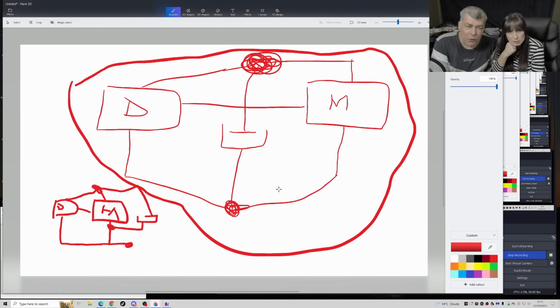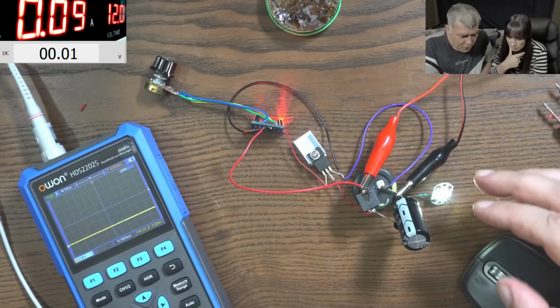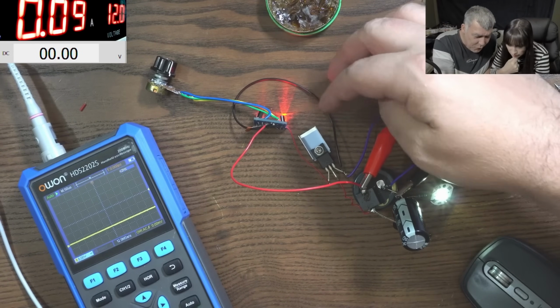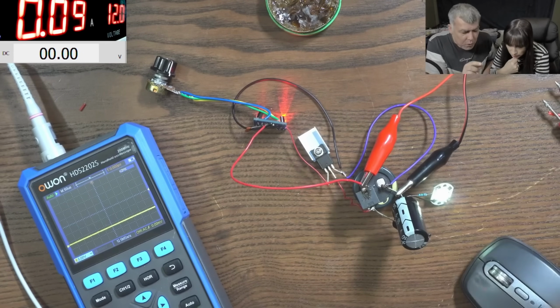So basically, what you have to do is be sure your PWM generator or driver is connected straight to the minus of the capacitor. So let's check together. Your minus is connected where? You see? So if you take this wire and you connect the wire exactly here on the minus of the capacitor, you solve the problem.